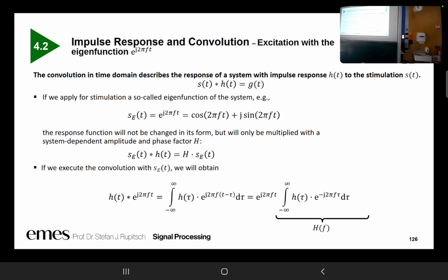However, the problem in the case of a chirp signal or such a sweep signal is that the combination of the sampling points and the sweep has to be chosen in a very intelligent way, because you want to capture several frequencies, and if you perform the sweep really fast, then you won't be able to capture all frequencies. So you have to more or less know the system already. The decisive point is the time bandwidth product.